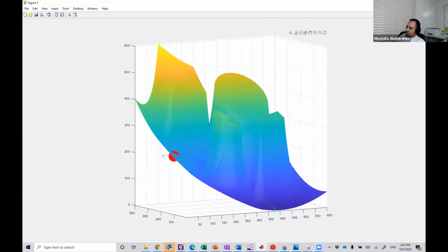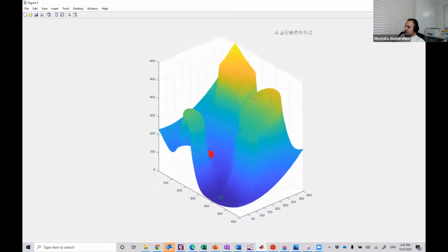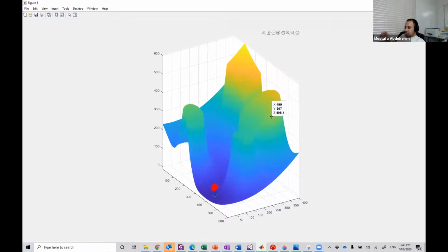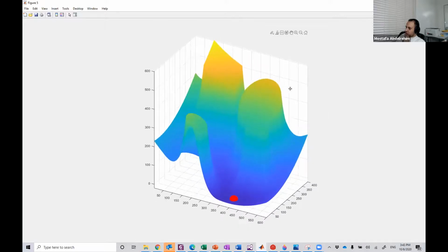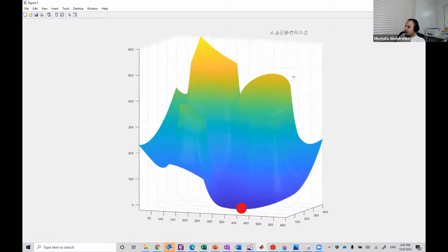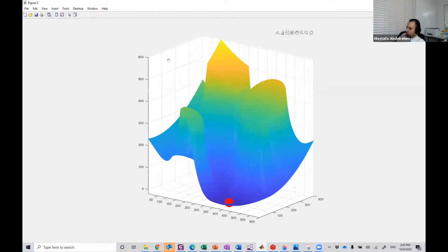So half of the ball is under the map actually, because the center of the ball is the location at which the robot will go, the point in the X and Y points in the route. So to make all the ball above the map, we should lift it up by its radius. We should shift it up by its radius in the direction of Z. This is the dimension that has the problem, the Z dimension.